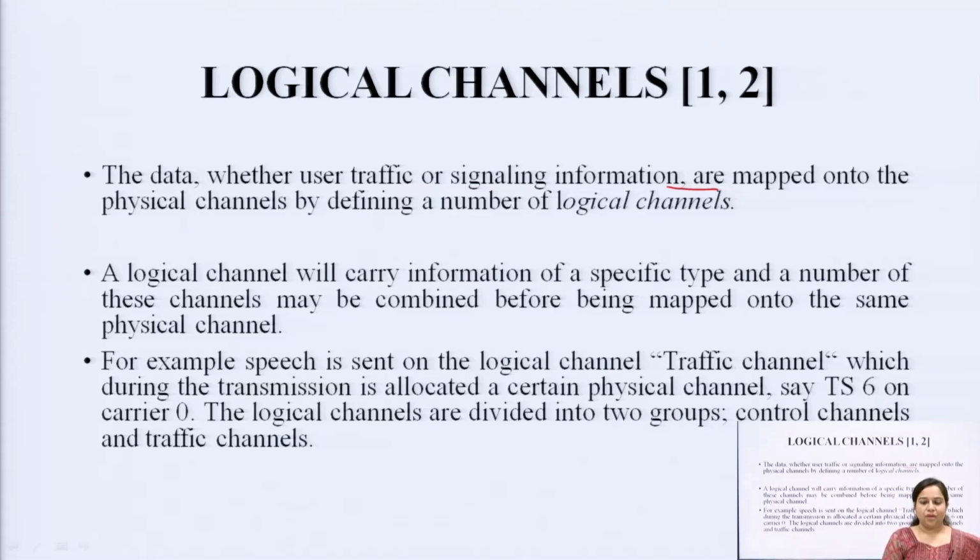So, whatever carrier signal we have used at the transmitter side, the same has to be used at the receiver side. So, what it does, it will provide the synchronization, and if it is different from what we have used at the transmitter side, then the received signal, the demodulated signal will not be the same as the original signal that we have modulated. So, in that case we require synchronization bits when we are talking about digital communication, and signaling information or a synchronization signal in case of analog communication.